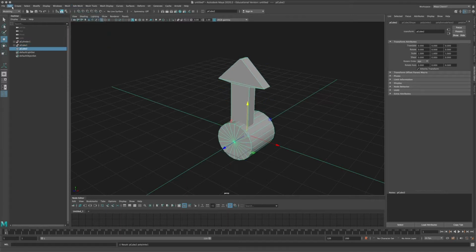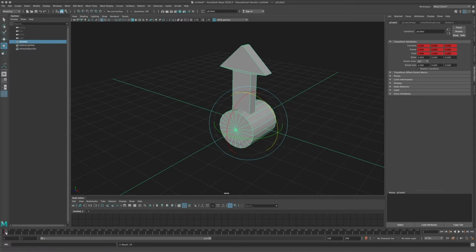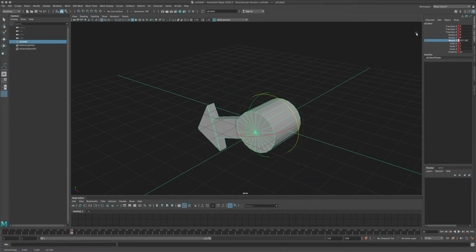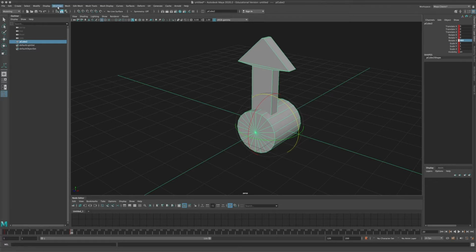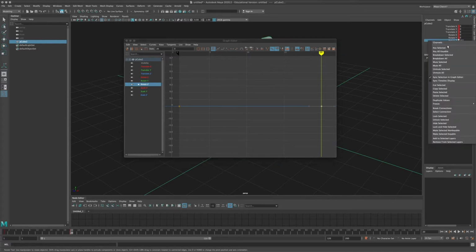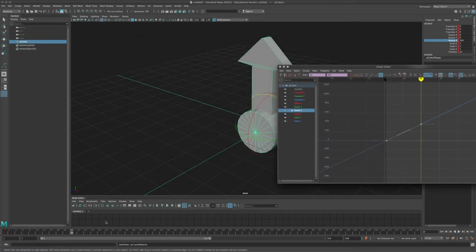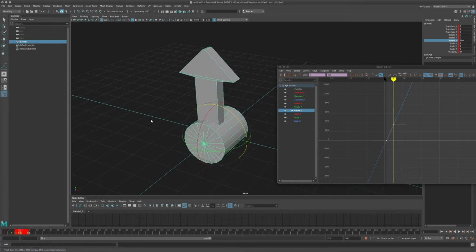I'm going to combine these two to a single shape, delete the history, so we can rotate that. And in fact, we're going to do that. So let me just put another keyframe on frame 20. And it's rotate Z, so let's put that to 360 degree and go back to the graph editor. Oh, it's always going to open on a second monitor, apparently. Why ever? Rotate Z, and is it actually rotate Z? No, I didn't set a keyframe, so yeah. So that's that. So linear. I'm just gonna set post and pre-infinity. So that's just your standard rotation animation that will just keep constant over time.